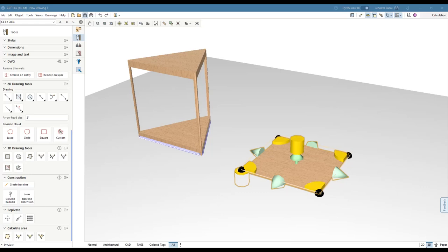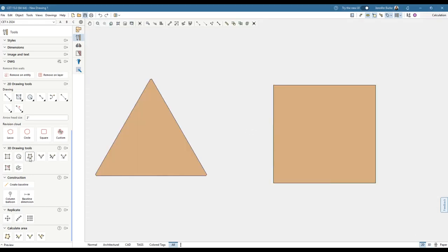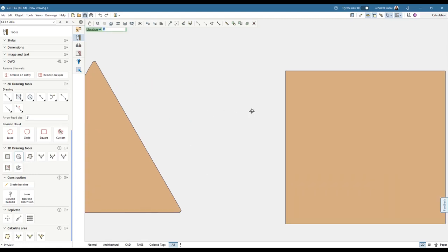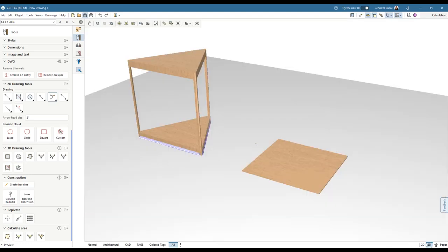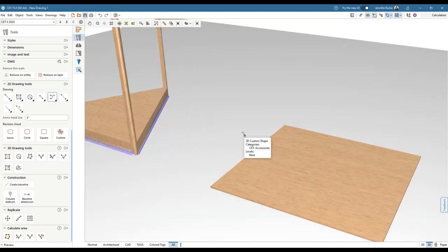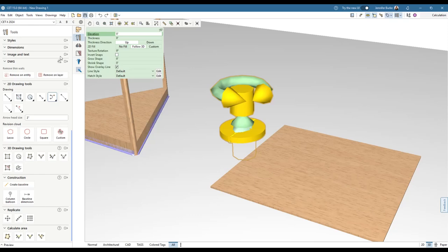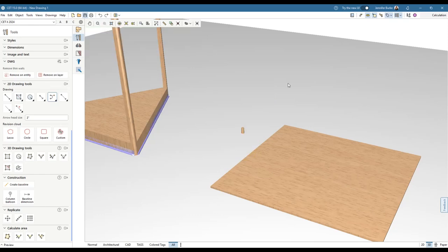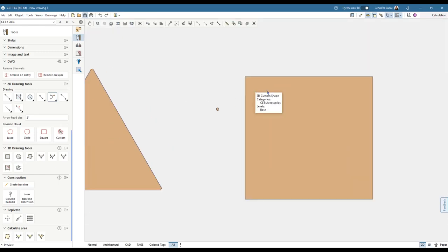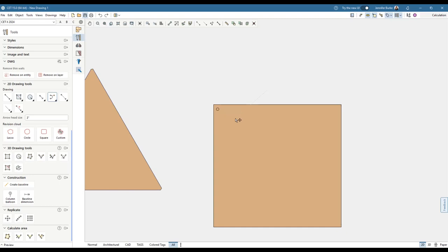Next, we're going to head over to 2D, and we're going to create a perforated hole circle. There could be multiple ways to do this, but I'm going to draw a 3D circle with a radius of 0.25. And then I'm actually going to give it a thickness so it protrudes through that perforated steel plate. So let's actually just do that as a 1 inch. So it should look like this. We're then going to eyeball it. Again, there could be multiple ways to do this, but I'm going to move that square over that top left corner of the circle, so it kind of looks like that.